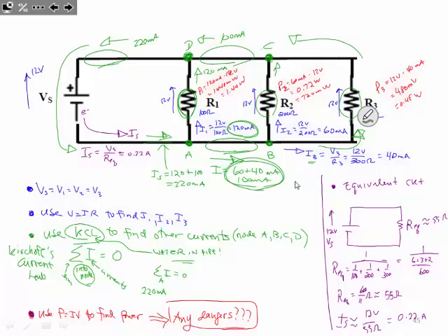What do you think that is? They're negatives. Minus 100 coming out, minus 120 coming out, that should equal 0. Does it equal 0? Yeah, it equals 0. So there's an example of what Kirchhoff's current law says. But it's logic, it's water in a pipe type of logic.